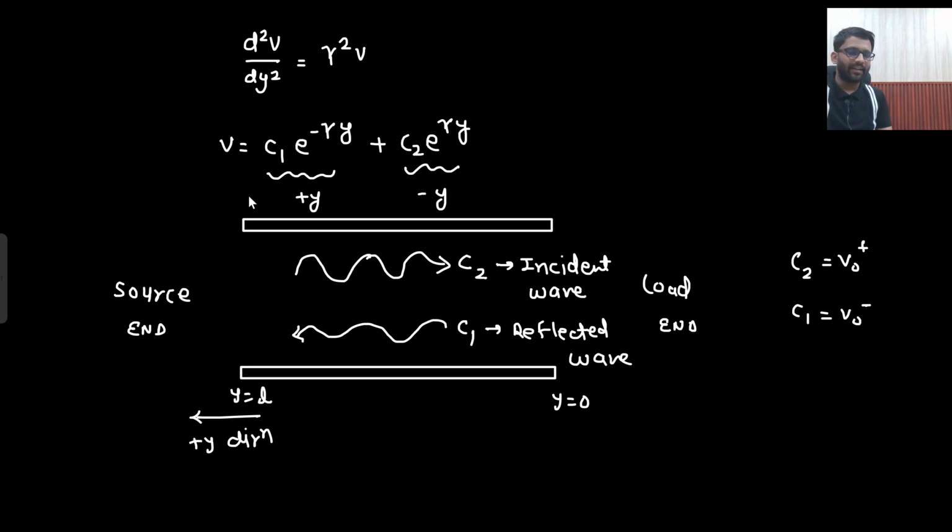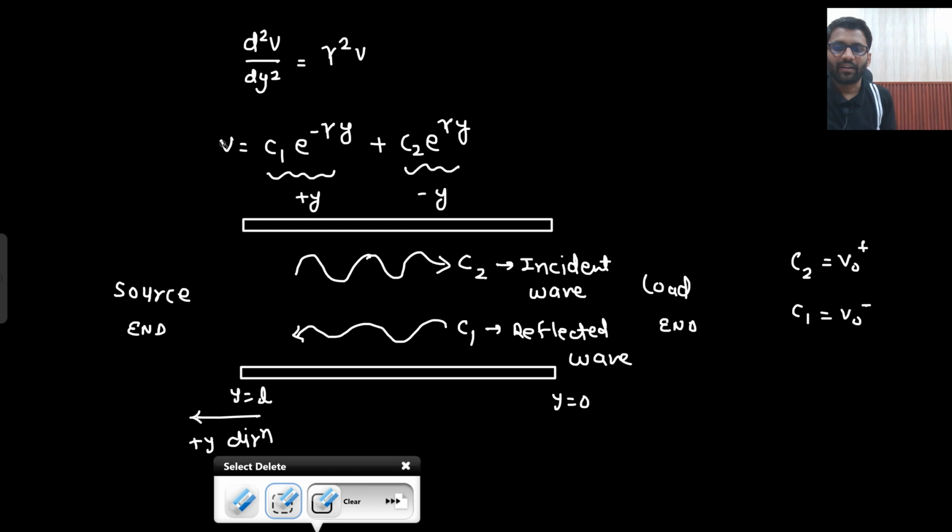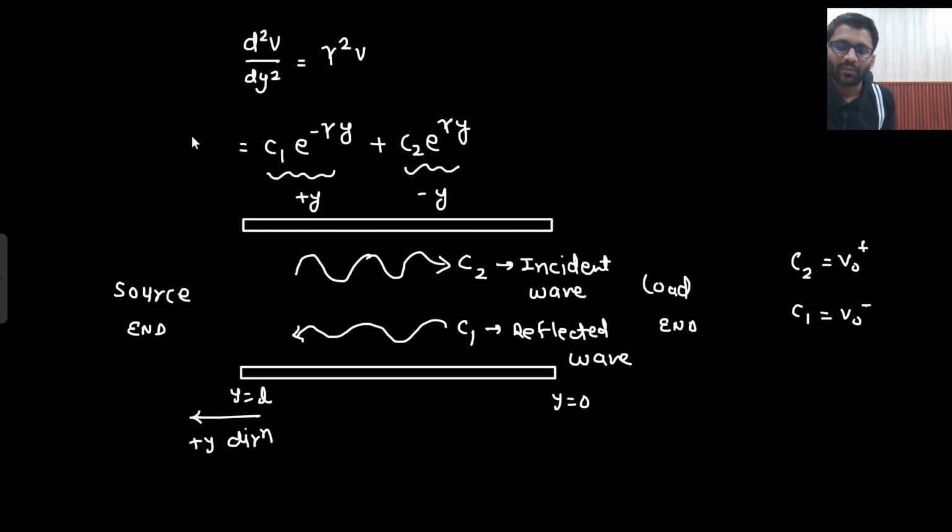Okay, we did the complete derivation, we got the V expression in terms of y. So I am going to write it down, Vy. My Vy is C1 e to the power minus gamma y plus C2 e to the power gamma y. So I cannot keep C1, C2. I need to write down the value of C1, C2, then only I can get the complete expression.